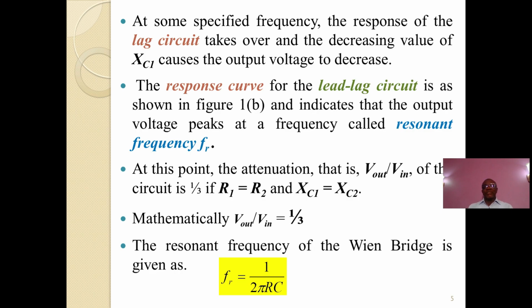Now, at some specified frequency, the response of the lag circuit takes over, and the decreasing value of C1 reactance causes the output voltage to decrease.